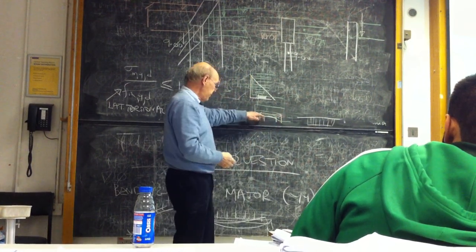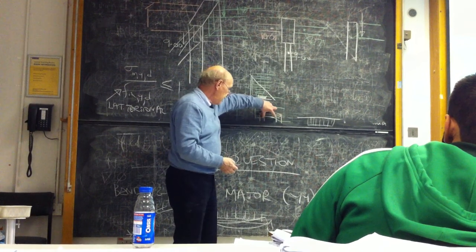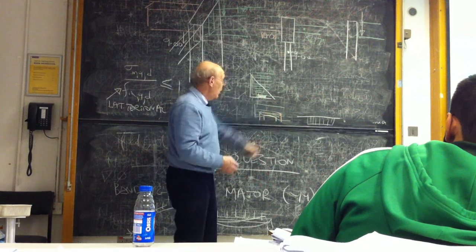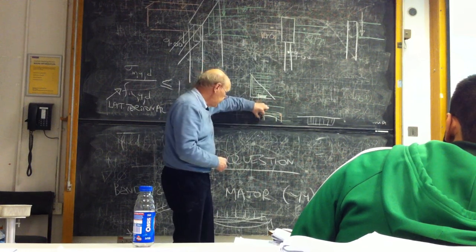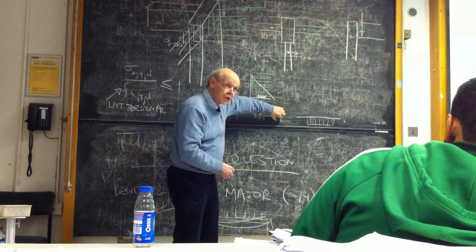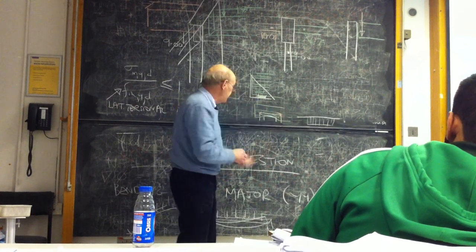The effect of having to bend the fibres is to enhance the effect of this as though it was that wide. Now what the code also says is that that distance must not exceed 30, and that distance must not exceed 30. It might be even less.